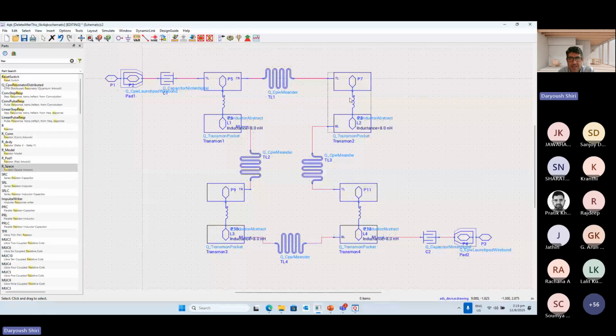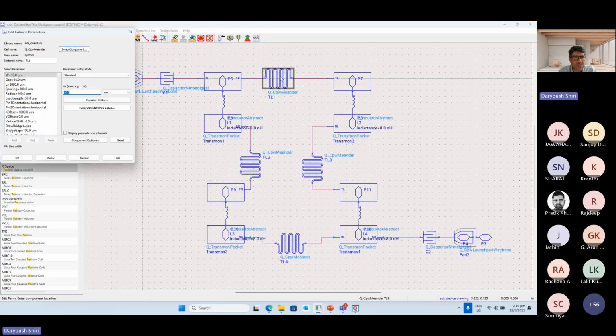So, okay, I adjusted the gap of this one, the gap of this one, everything is default. Only the length of the resonator. This resonator on top is supposed to be W and G is 10, 10. We just keep it like this. We don't optimize it for 50 ohm. This is 600 micrometer. And let me see if the offset is 1600. And yes, vertical shift was 100.